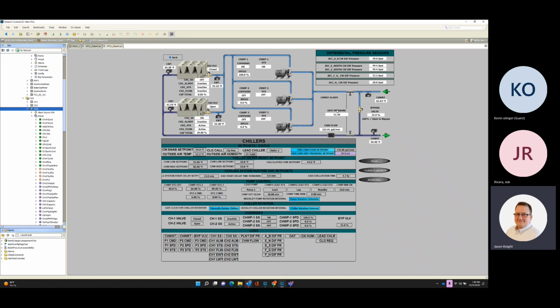And then as we got the kids into the building and learned the load that way, went through the loop tuning for the chill water side, I was able to get the pressures down more and figure out the minimum flow set point. But now I'm going to have to basically start over from scratch and do the same thing for the heating system over the next week or two. So I'm anticipating handing this over to you, like first, second week of November, maybe in there.